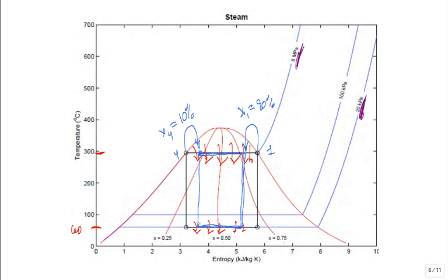And if I did that with a smaller rectangle, somebody says, I want to know how the thermal efficiency of the original, bigger system, with the corners at 1 and 4 on the saturated liquid, saturated vapor line, compares with the new one, where I moved the corners so that 4 is now 10% and 1 is now 90% quality.